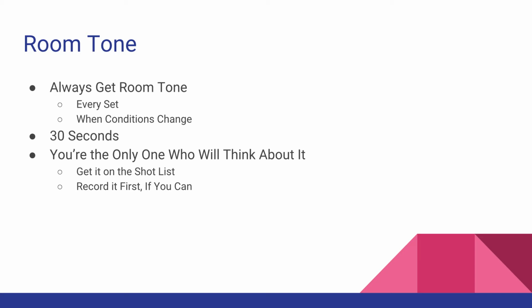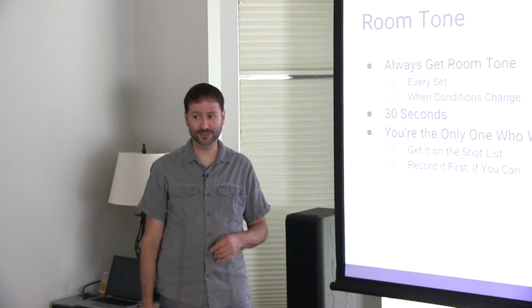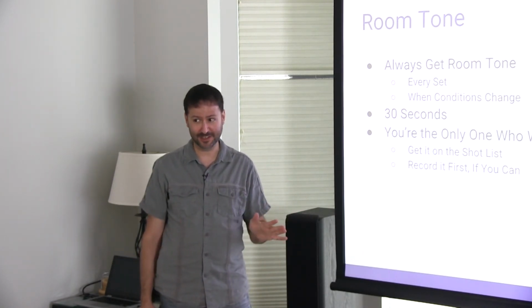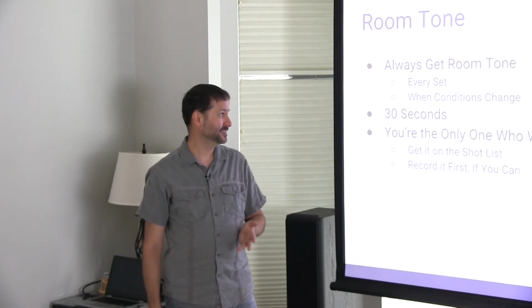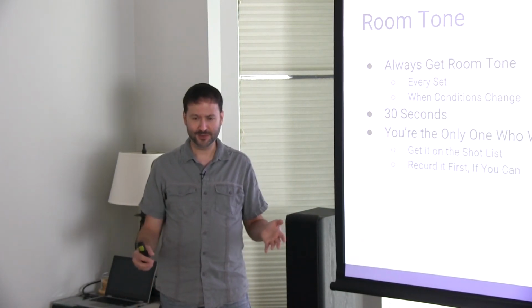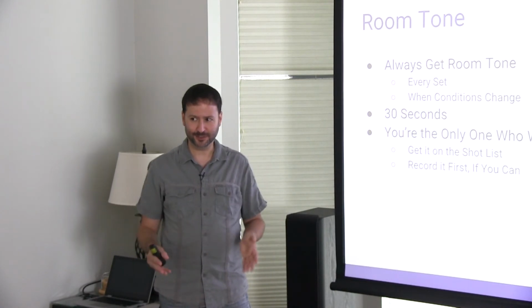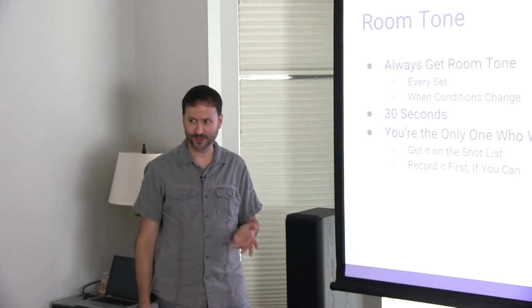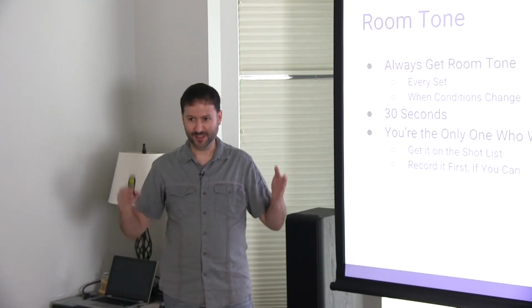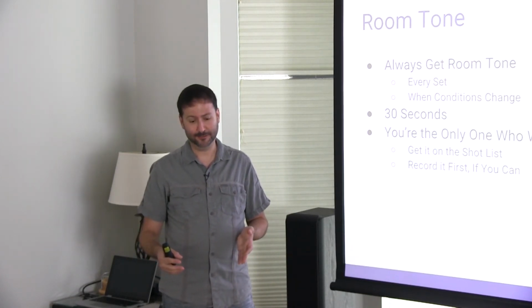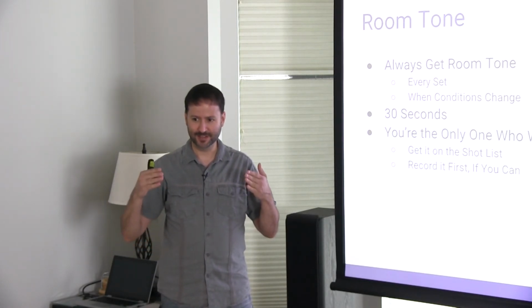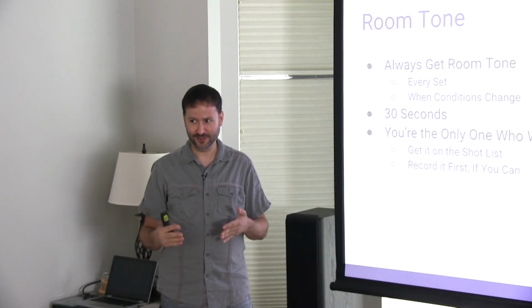Okay, always get room tone, and I'm really guilty of this because it's so easy to forget about it, especially if you're an ADD audio guy, because no one is thinking about it, and to get room tone, you have to get everyone else to stop and not make noise for 45 seconds or so while you do it, and the perfect time to do that is the first thing, but I have explicitly asked for that and been told many times by directors, no, we'll do it later.